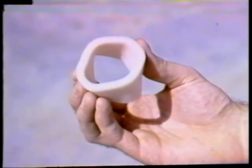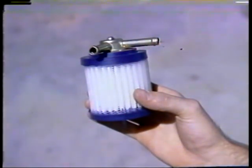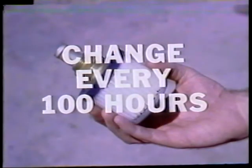On vacuum installations, a polyurethane garter-type filter surrounding the regulator air inlet located out of the engine compartment prevents contamination from entering the system at this point. A central air filter mounted on an instrument's air inlet removes contaminants such as tobacco smoke before they can damage instruments or the pump. In pressure systems, the air comes from an area less susceptible to smoke and dirt, thus reducing the danger of contamination. These filter elements, however, should be replaced every 100 hours or as recommended by the manufacturer.